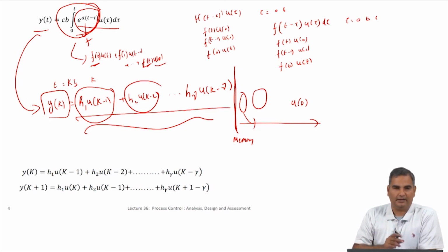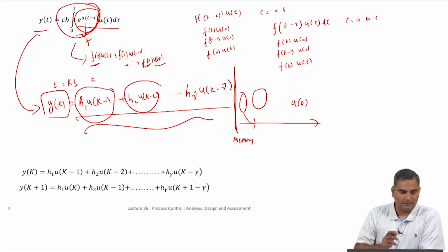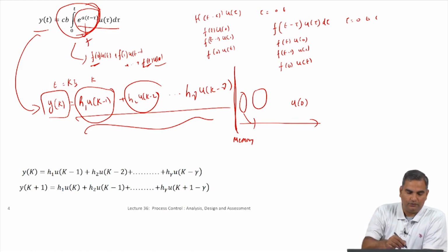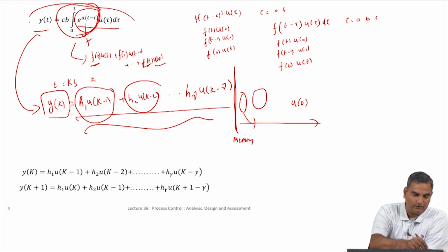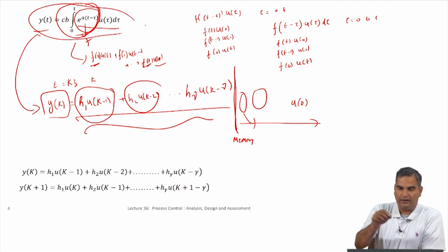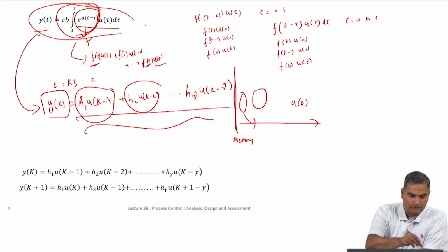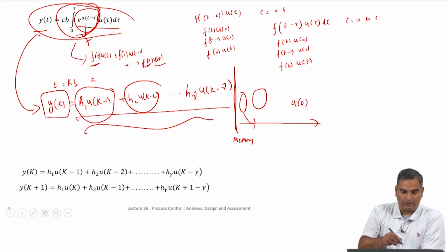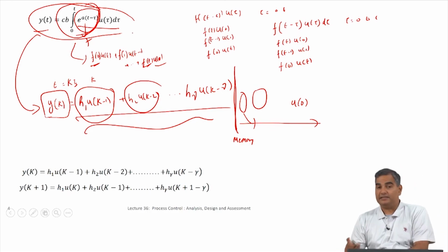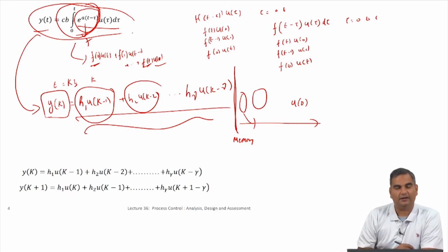Actually, under certain conditions and under certain assumptions, you can show that even if you integrate this equation with continuous u, where the u is changed in a stepwise fashion, and then you actually do this integration, and then actually compute yk at those time samples, you can show that this and this will be exactly the same under certain conditions. Okay.